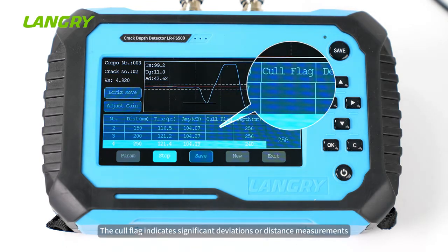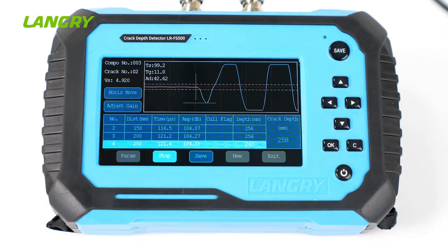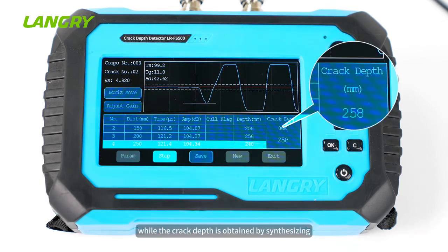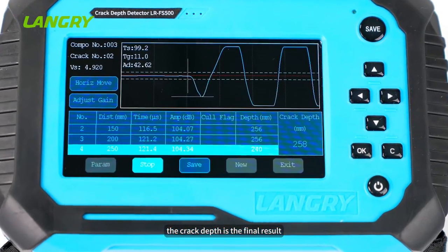The cull flag indicates significant deviations or distance measurements that do not meet the requirements of the procedure, and points with cull flags are not included in the calculations. Calculated depth refers to the depth of the crack calculated from one distance measurement, while the crack depth is obtained by synthesizing the calculated depths from multiple distance measurements. In other words, the crack depth is the final result.